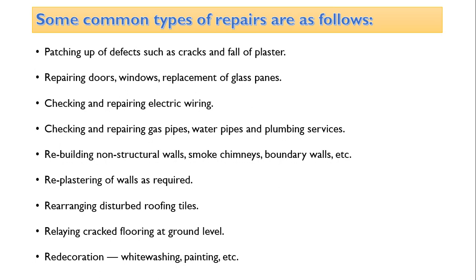Redecoration, whitewashing, painting, etc. Sometimes whitewashing is done to the structure. After one rainy season, you will find patches or fading of the color. It should be repaired. Painting, again, if cracks are there or paint has fallen, it should be repaired. So this comes under repair.